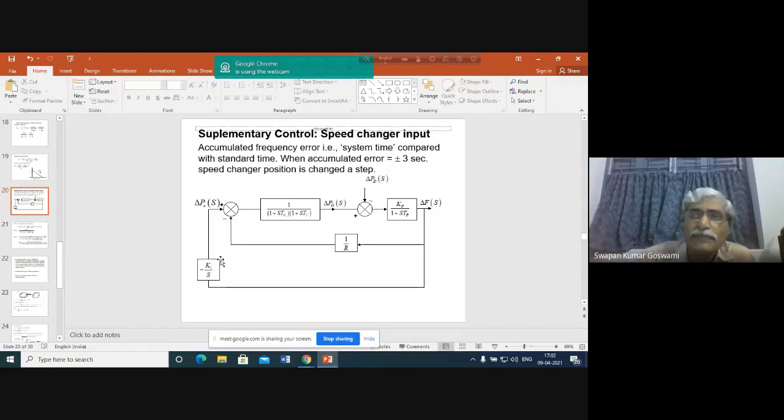So finally, you can see that frequency control is the responsibility of this generator or this power station, where the supplementary control will be implemented. But initially, as the system load changes, all the generators deviate from their initial setting value. That means they are following the load. They are taking the function of load following. Following the load, they are changing their power output. When there is more demand, they increase their power output, at the cost of system frequency.